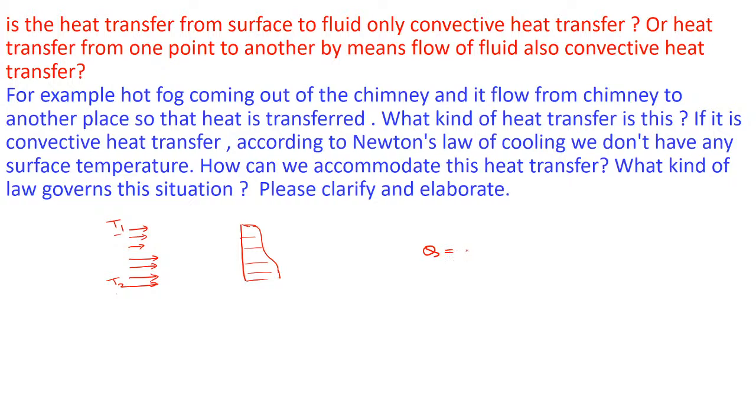So we can find the heat transfer rate Q as just m dot cp into delta T, where delta T is the temperature difference, and at steady state this is the heat transfer between these two fluids. If you are interested in the final temperature, then Tf is equal to M1 C1 T1 plus M2 C2 T2 divided by M1 C1 plus M2 C2.